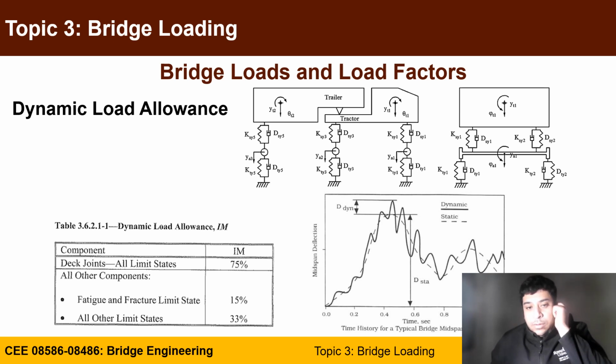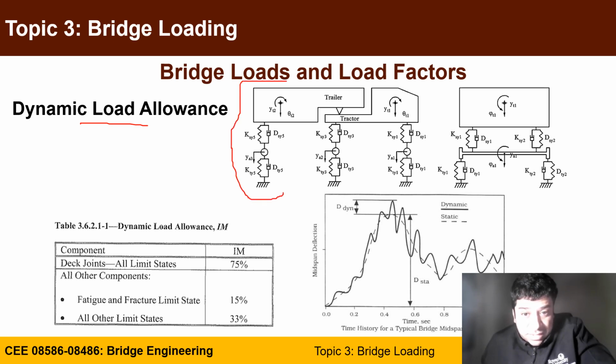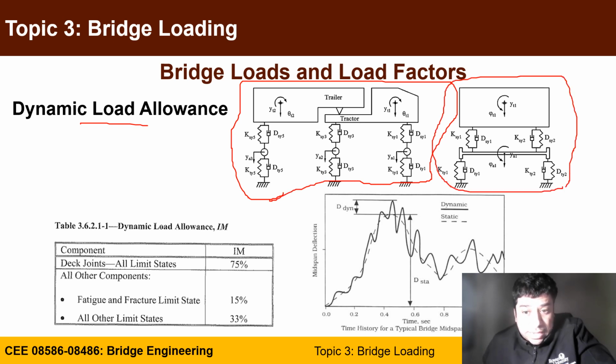We need to account for the dynamic load allowance. What we discussed earlier is your truck is not moving at an extremely slow speed to be considered static loading. It moves with speed and has a dynamic effect on the substructure and superstructures. So you have a series of spring and damping systems in any truck. And there is huge research done to get those numbers on how to amplify your weight, which can be considered static, by a factor to consider dynamics.